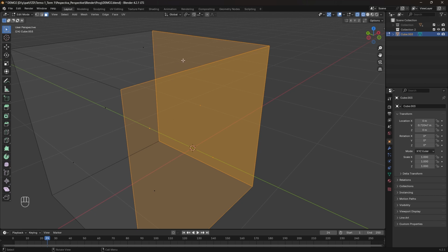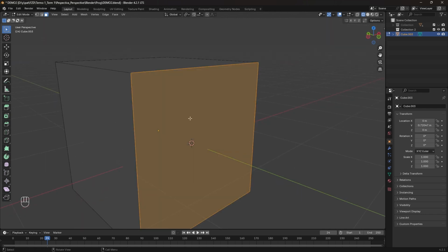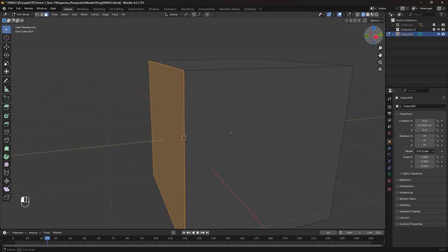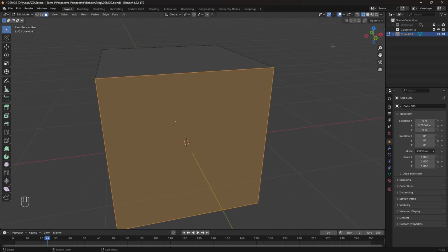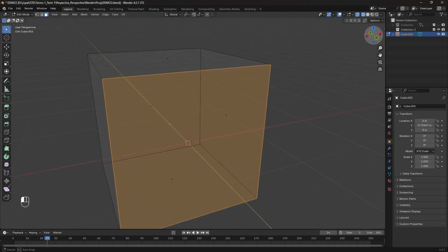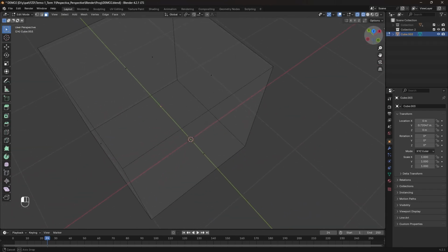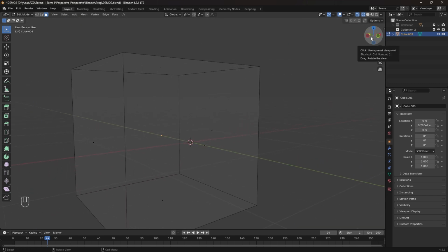And again, you can see that when I'm selecting this one and like this, I'm selecting these two faces because I'm using Alt Z. So with Alt Z, if I was using the normal mode and selected this face, I would just select this face and the other one would not be selected. But with Alt Z, we basically enable the transparency mode, so we can see through the object. So this is the face stuff. Okay, and over here you can perform the same actions.